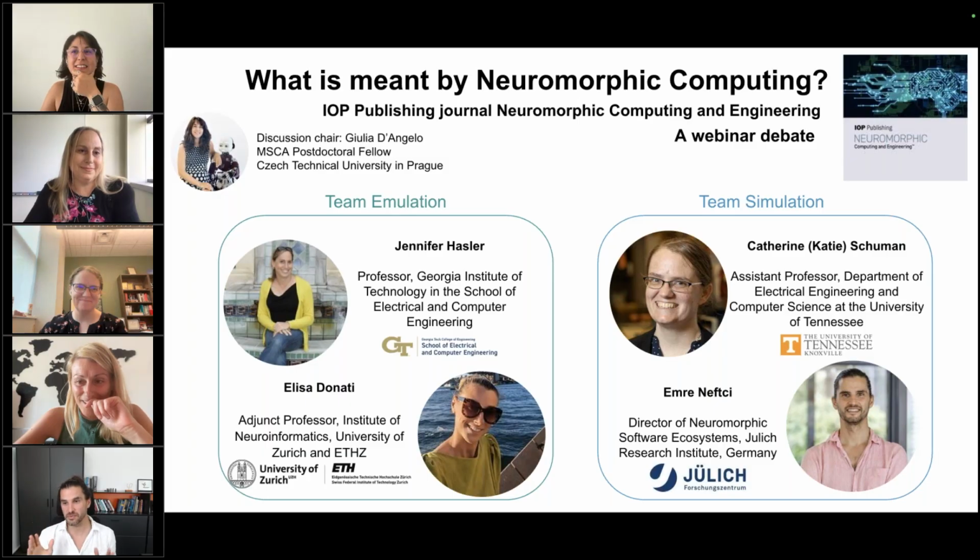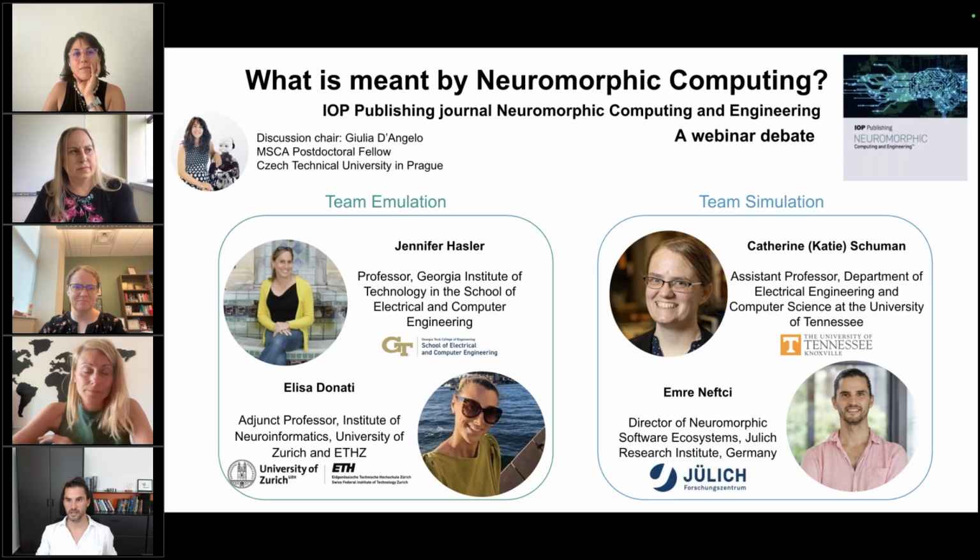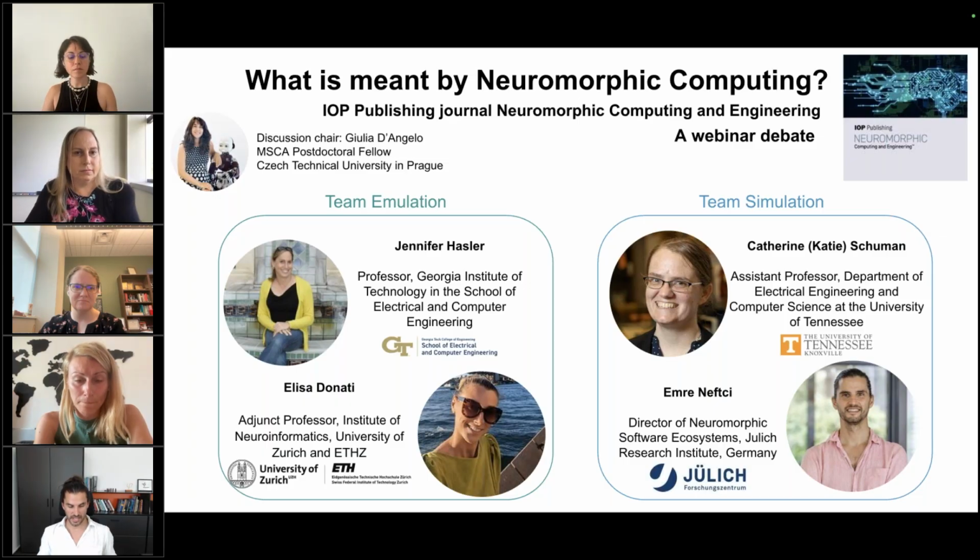Okay, so here's what I mean. Let's say I want to have a fast memory or a very long memory. If I want to change the timescale of that memory, I can just decide when I change my bit on my SRAM. It's completely arbitrary. For as long as my memory is powered, I can keep that memory there. Whereas in an analog system, I actually have to build a specific circuit for every time scale, and that just doesn't seem practical.